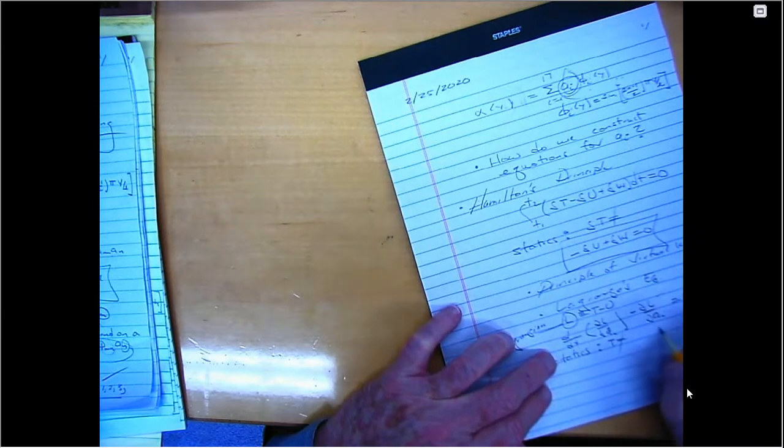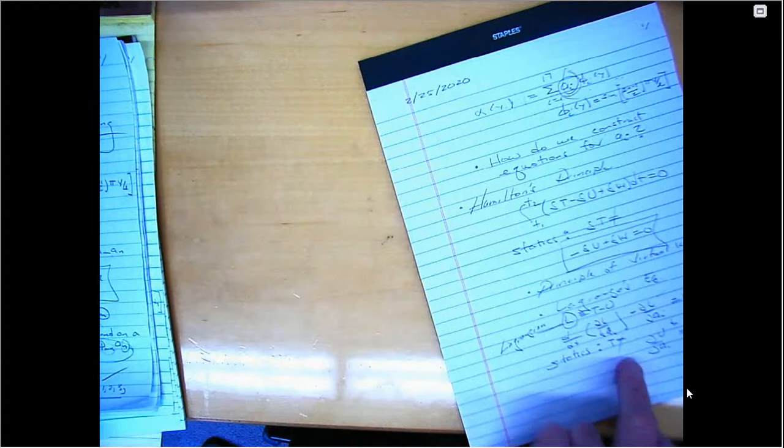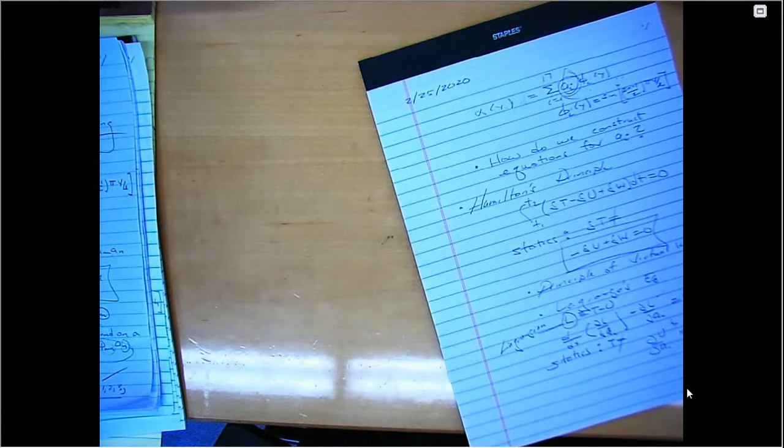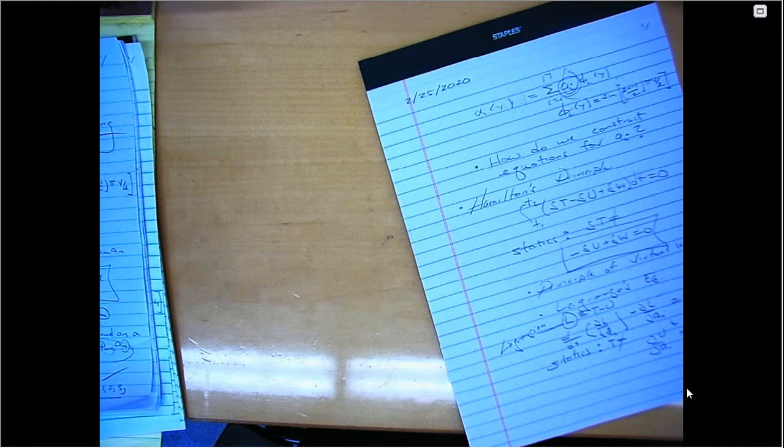And so this becomes partial U with respect to A sub I equals Q sub I. Okay, so that's the static form of Lagrange's equation. I was trying to give my compatriots in Italy all the credit they deserve. This is sometimes called Castigliano's theorem and is usually taught in sophomore, junior year in a course on statics.